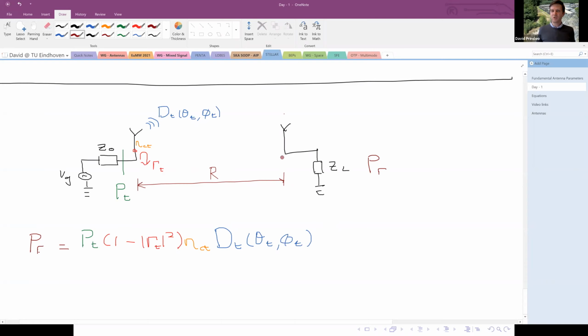To account for the free space loss, remember that the signals expand spherically. So there is a loss in signal magnitude just because that physically happens, and that's called the free space loss factor. This is the free space loss, so that term is accounted for as well. Now the signal has transmitted from this antenna up to this point here.